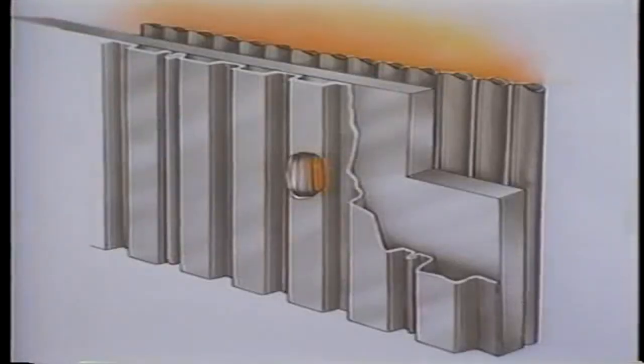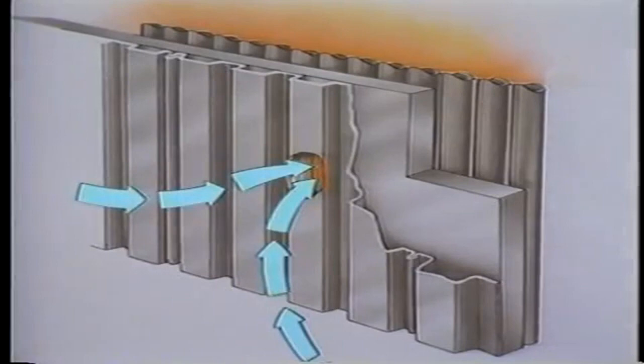Once in a great while, a leak will develop in the boiler casing. The severity of the leak and the design of the boiler will determine the action taken by the operator. Balanced draft boilers, for example, operate under a slight negative pressure. For the most part, any leak in the casing will draw air into the boiler.